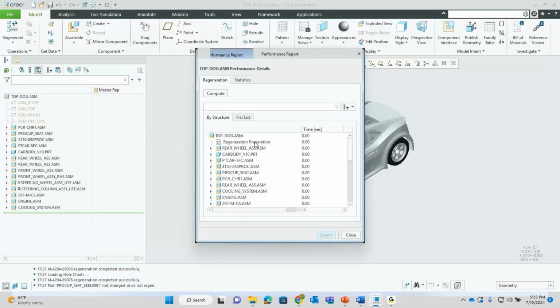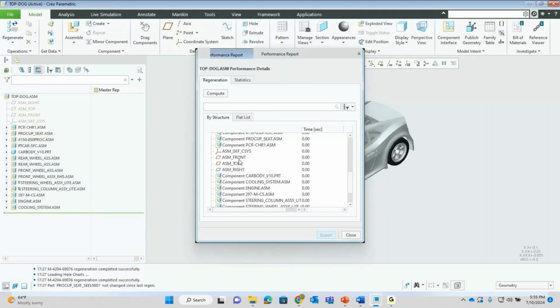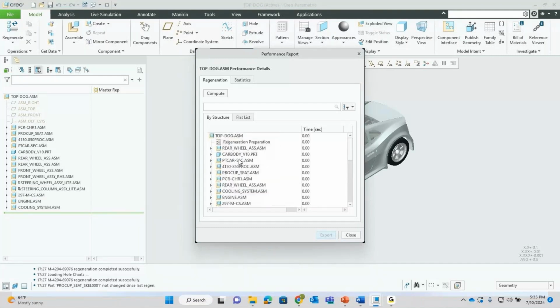And you can see that it picked up all the assembly, all the parts, sub-assemblies and things that are already in here. One thing that you'll notice as I work through this assembly is that it was done with proper top-down design tools. So we have a lot of skeletons in here. We have a lot of copied geometry. So it's really a good example of how you need to do your large assemblies in a real-world environment. So more or less like you guys will do it in your production environment. I've tried to mimic that as far as possible.